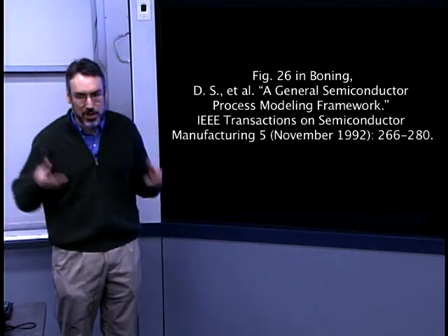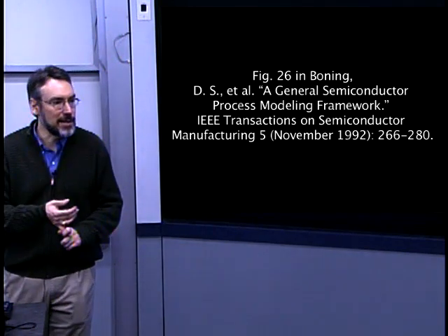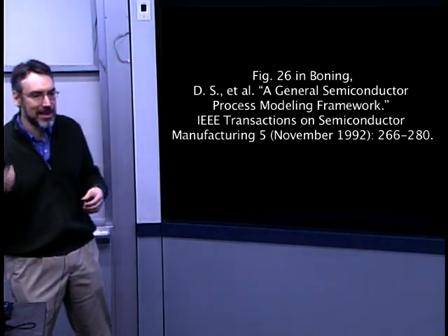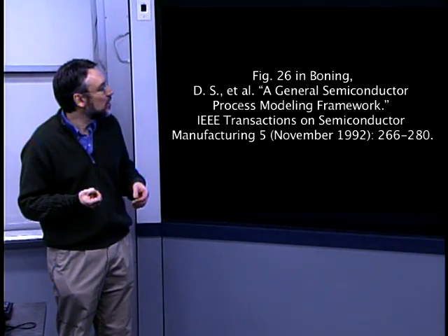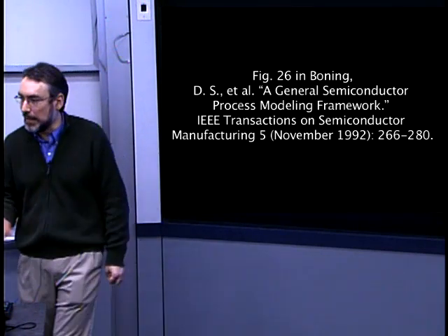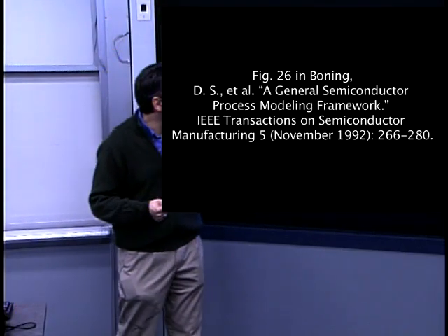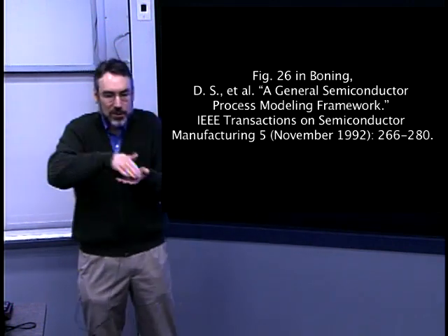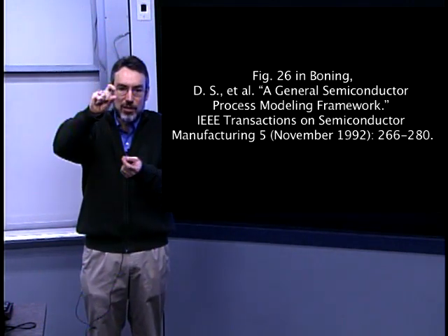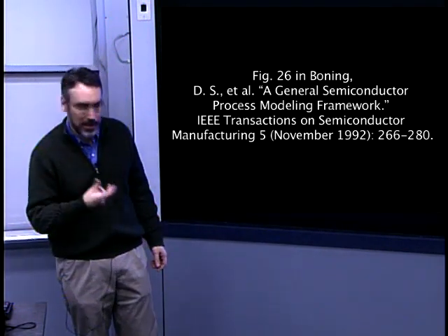We've got inputs in terms of the environment that we create around the wafer, that vacuum process, the chemical etchants, the gas ambient used in plasma etching, and then other control factors on the machine or the facility, things like thermal control in photolithography to be able to ensure that there's not thermal expansion of the components. And then we get changes in many of these wafers, many of these states. Many of these are desirable. We saw the change in the wafer state in terms of the geometry, as well as things like doping processes that change the conductivity of the silicon layers.